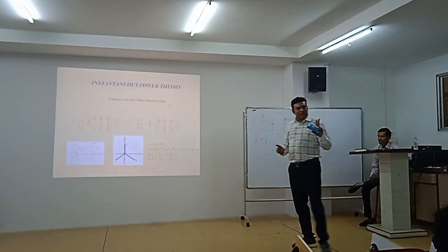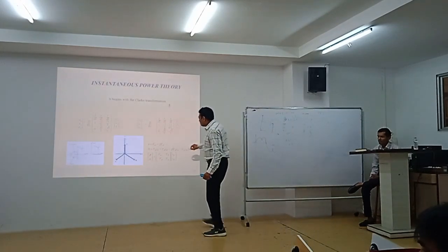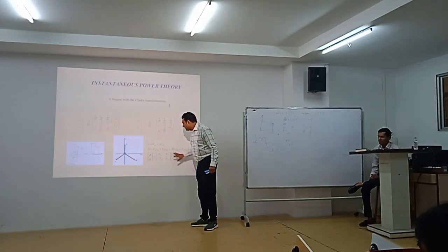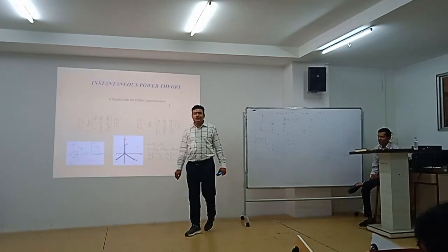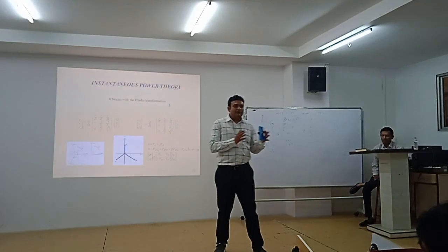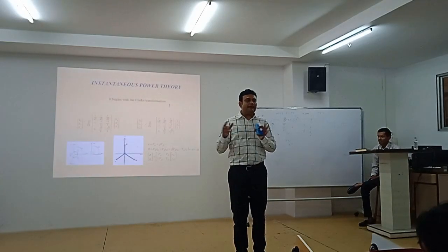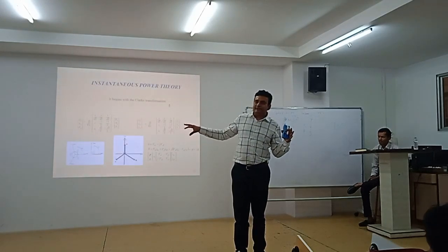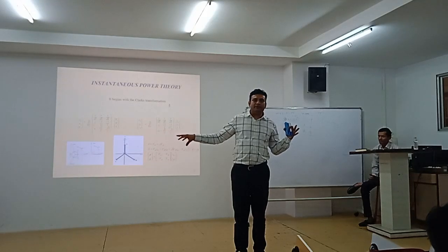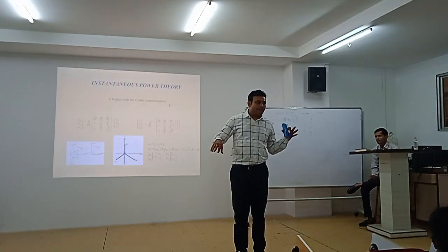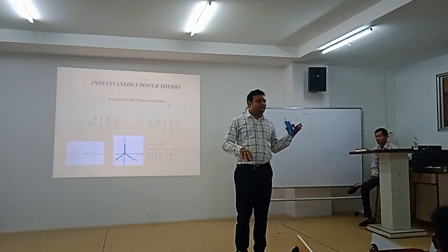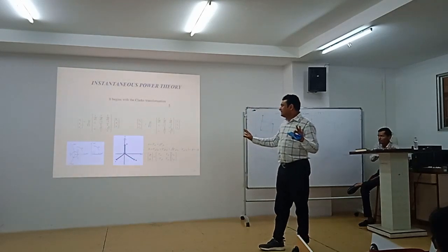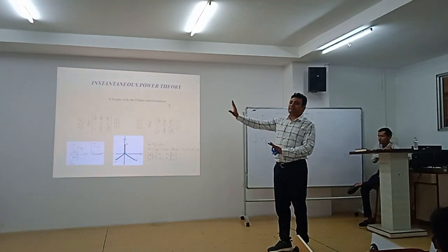Both 2 phase voltages, 2 phase currents. So V alpha, V beta, I alpha, I beta, and multiplying it converts into active current, active power, and reactive power, right? So here it is an assumption that reactive power incorporates harmonics also. So if you take only active power, it allows. I mean, instantaneous reactive power theory is efficient up to a certain extent.